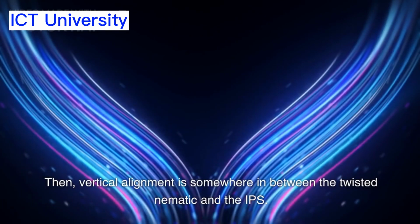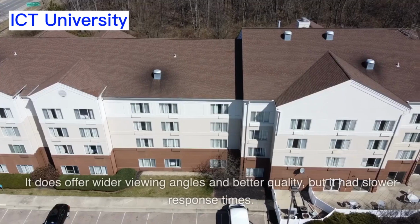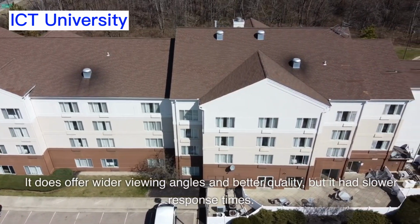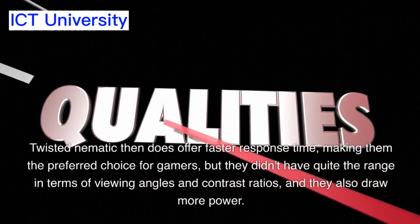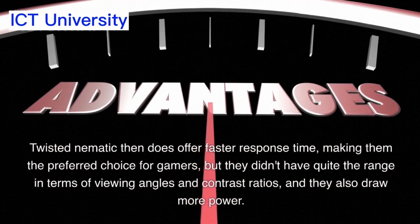Then, vertical alignment is somewhere in between the twisted nematic and the IPS. It does offer wider viewing angles and better quality, but it had slower response times. Twisted nematic then does offer faster response time, making them the preferred choice for gamers, but they didn't have quite the range in terms of viewing angles and contrast ratios, and they also draw more power.